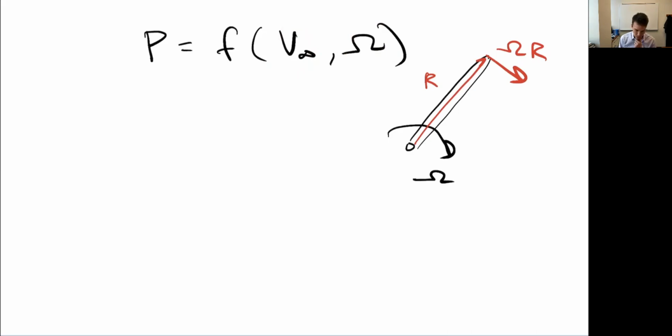So we could form a relationship. Let's call this non-dimensional parameter lambda, a ratio of this tip speed to my forward speed. That's clearly going to be a non-dimensional group, because I've got speed divided by speed. And in fact, this is the convention in the wind turbine community. It's called the tip speed ratio. But keep in mind, we could do any other sort of ratio. That'd be fine. It would change some specific numbers, but not the nature of these conclusions.